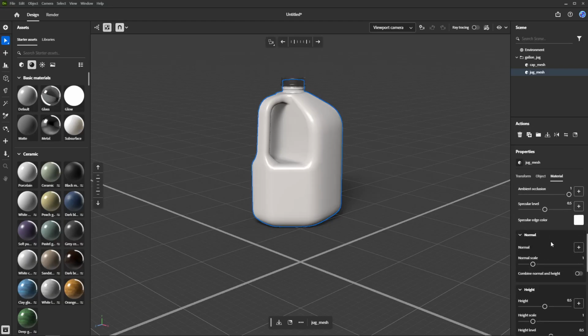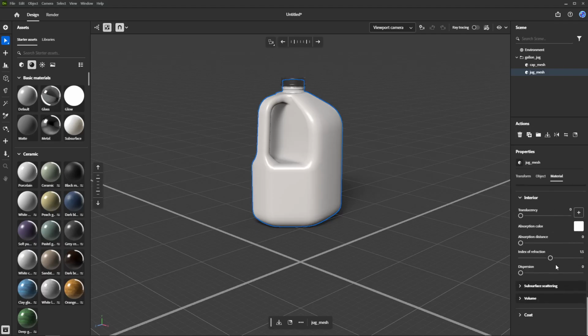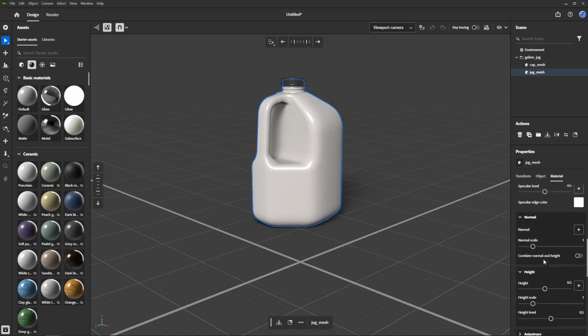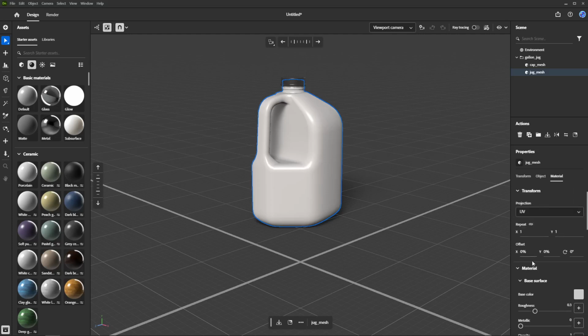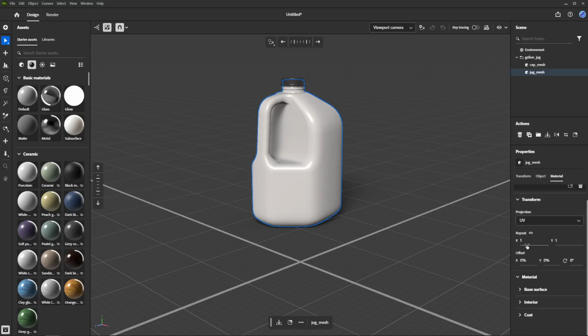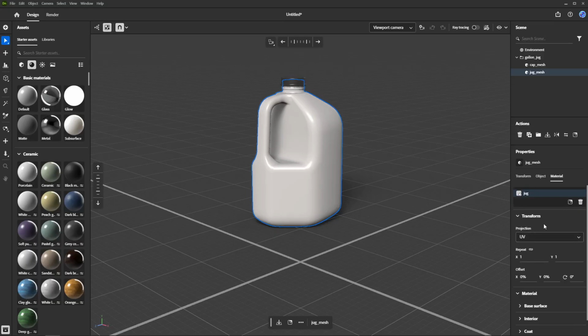According to official documentation, which is always a handy reference, the Material Transform properties allow you to control the overall position, rotation, and size of the material on the model's surface. This is where you'll do most of the legwork to tailor the texture to your liking. Here, you'll notice several controls at your disposal. Size or scale, which might sometimes be labeled as repeat or tile, rotation, which usually allows for inputs in degrees, offset, or position to fine-tune its placement using XY offsets, and possibly even options like mirror or flip for playing around with symmetrical patterns.